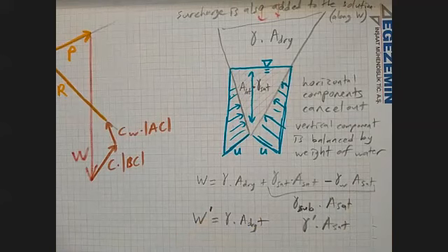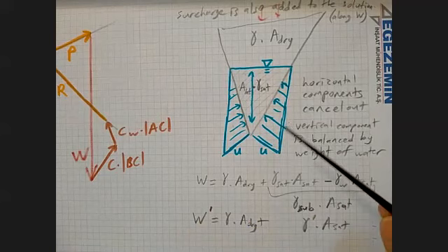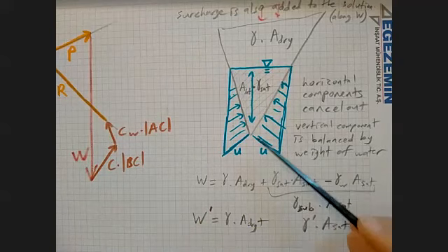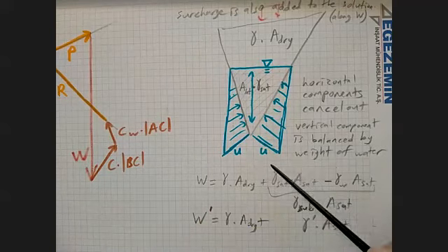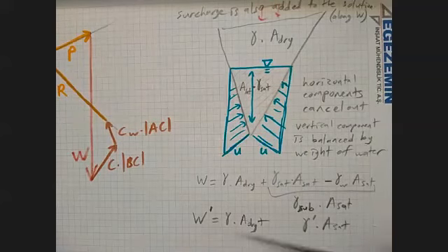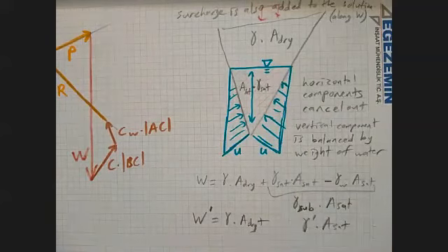So the way to deal with water in your wedge, if you are doing a drained analysis, because remember the previous chapter, you can do a drained analysis or undrained analysis. If you are doing a drained analysis, you need to consider effective stresses and pore pressures. If you are doing undrained analysis, everything is saturated, everything is total stresses anyway.